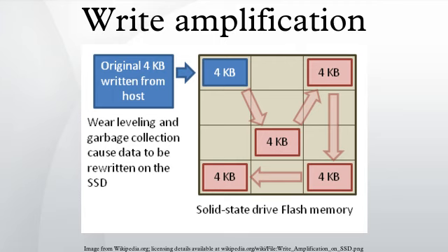If the data is mixed in the same blocks, as with almost all systems today, any rewrites will require the SSD controller to garbage collect both the dynamic data and static data. Any garbage collection of data that would not have otherwise required moving will increase write amplification. Therefore, separating the data will enable static data to stay at rest, and if it never gets rewritten it will have the lowest possible write amplification for that data.